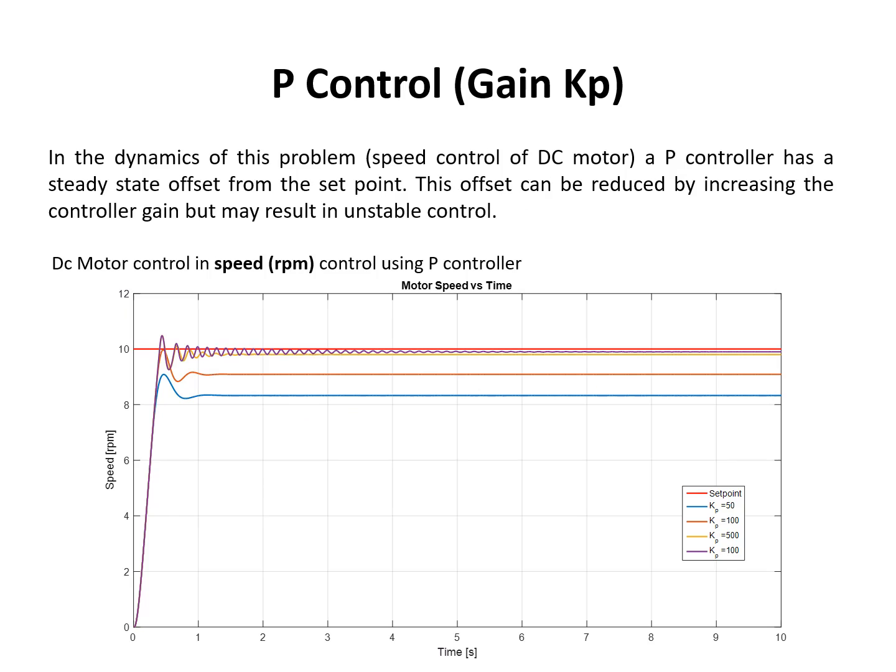So here is again the proportional gain, but now looking at it as a type 1 system. So this is a speed control motor. Again, we're not looking at the angle of the motor, we're now looking at the speed of a motor. And if you go through the dynamics, you'll see this is a type 1 controller. And we know from a type 1 controller, as Kp approaches infinity, we will have an error which approaches 0. But we will effectively always have a finite error with a finite value of Kp.